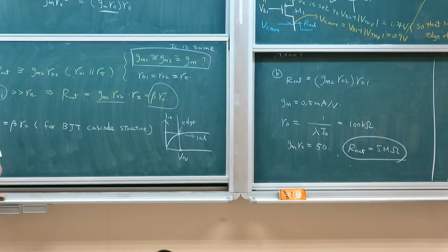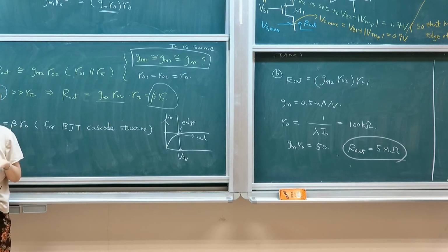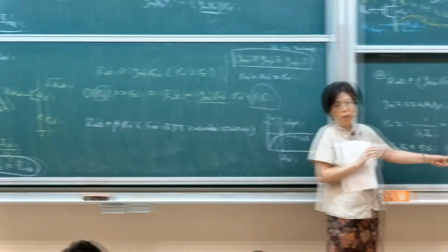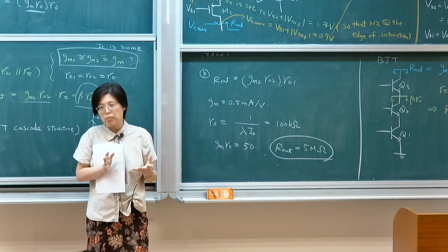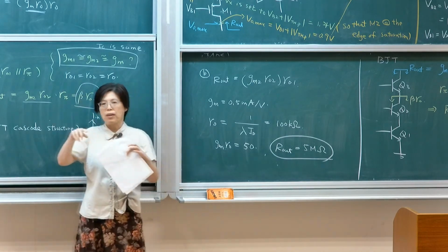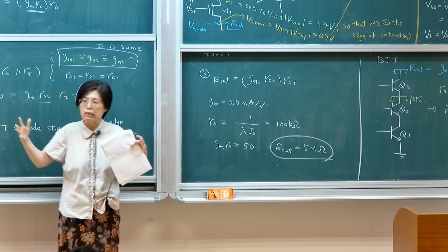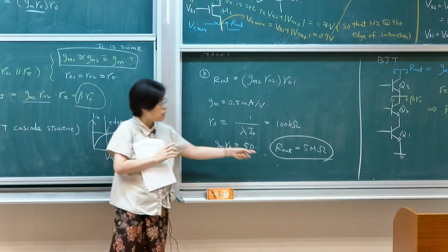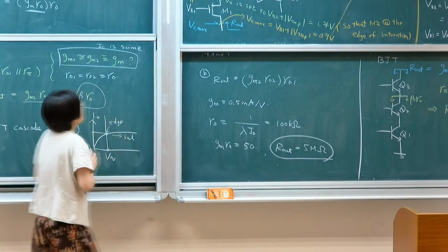If you ever did any tape-out examples, if I give you a resistor model file, for example, you will see that to create a 5 megaohm resistor is essentially impossible, or it's very, very area consuming. You use snake-like routing to get very, very large resistance. You need a lot of routing area for that to be realized. So this is a very powerful tool.